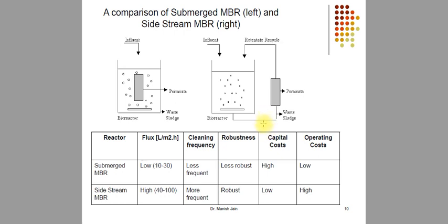Here you need to use some type of pump to flow the feed from outside the reactor, and then recycle it inside the bioreactor again. So you need pumps, you need tubing also. It may contaminate the reactant present inside the reactor, as well as kill the microorganisms. So submerged bioreactors are much more useful when you want to proceed with a specific type of reaction.